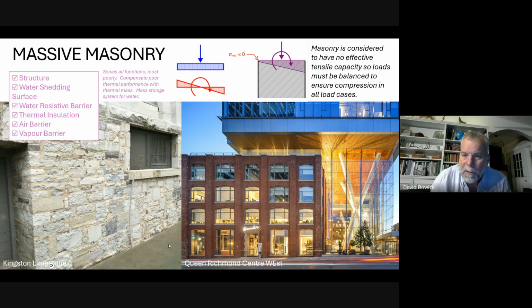So, spalling of the brick. What does that mean? You probably haven't encountered that. Brick gets saturated, the water freezes, and you know that ice takes up more volume than water. Water is one of the few substances that expands when it freezes, which is why ice floats. So it's expanding now inside the brick wall. If it expands too much, it'll actually break the brick apart, and the surface of the face of the brick will fall off. This is what's called spalling.